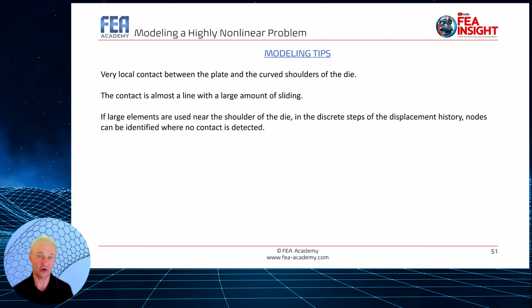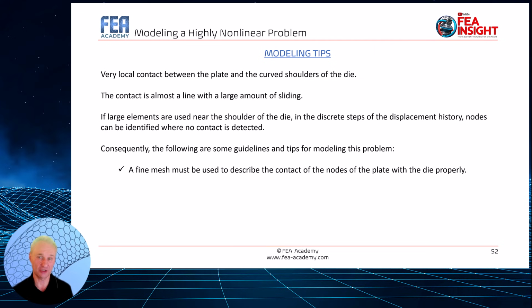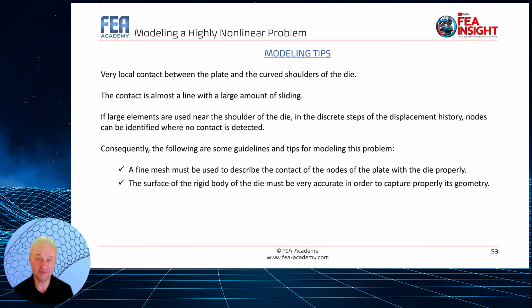So the following are some guidelines and tips for modeling this problem. First, a fine mesh has been used to describe the contact of the nodes of the plate with the die properly. The surface of the rigid body of the die must be very accurate in order to capture properly its geometry. So it means that when you create your surfaces, the geometry of the problem, it is very important to create very accurate geometry with your pre-processing software. Again, it is what I did, so if you need it, I can share with you the geometric file.